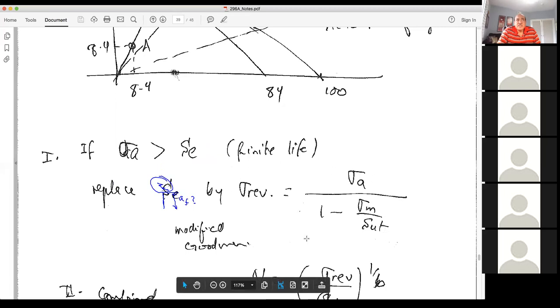This is the relationship that reflects the amount of damage due to the mean stress. So you subtract the amount of damage due to the mean stress, and therefore the equivalent fully reversed stress could be substantially higher than the alternating stress. This relationship is based on Soderberg, because Soderberg tells you that sigma alternating over sigma fully reversed